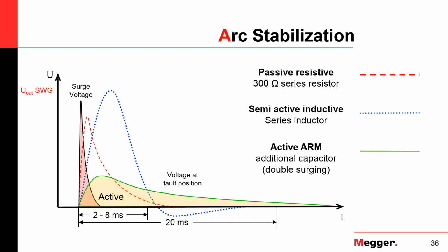Those are triggered TDRs. So now, if you think about the longer the cable gets, the more the runtime differences between the TDR pulse and the actual discharge of the high voltage source can become a problem. So the TDR has to be timed very precisely to actually hit the standing arc to reflect back.